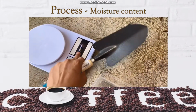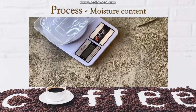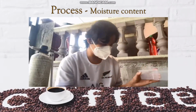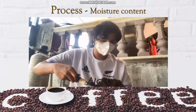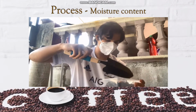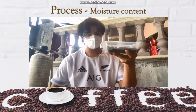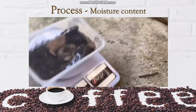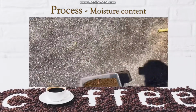Firstly, we need to weigh the empty container and record its weight. Now, we put the soil sample into this container. Then we measure the weight of the container and the soil sample. It is 297 grams. Now we will let it sit under the sun for 5 hours.